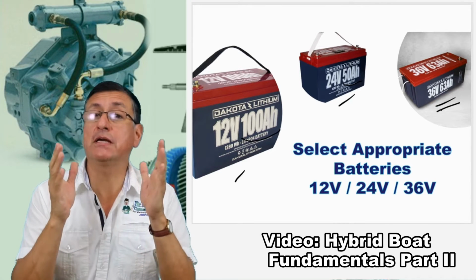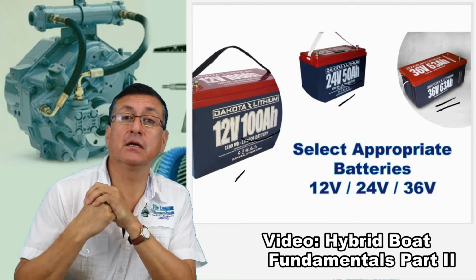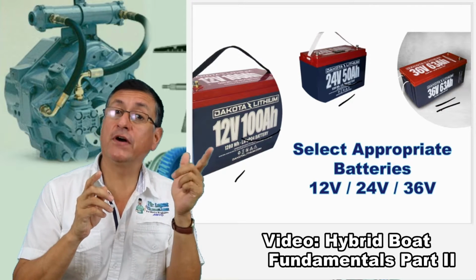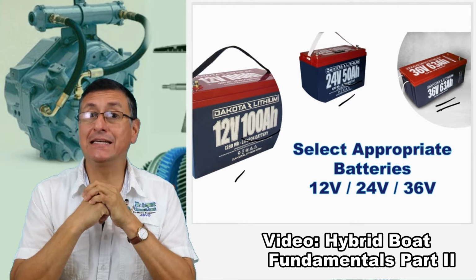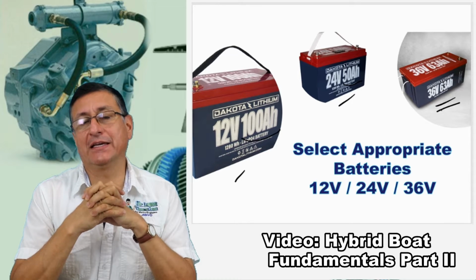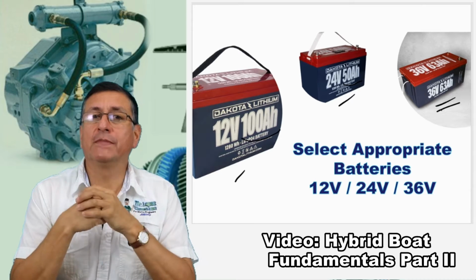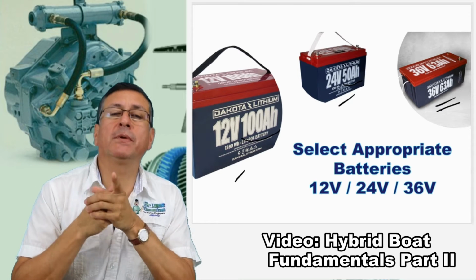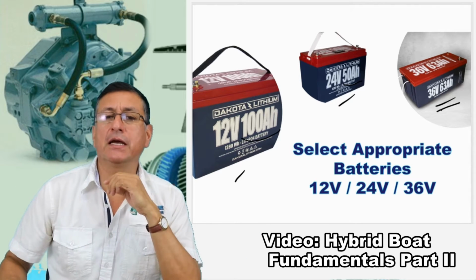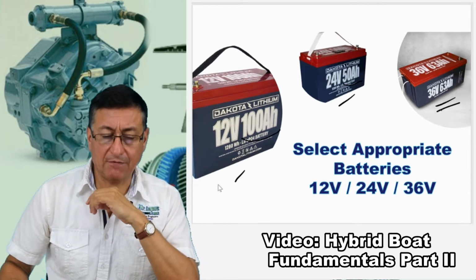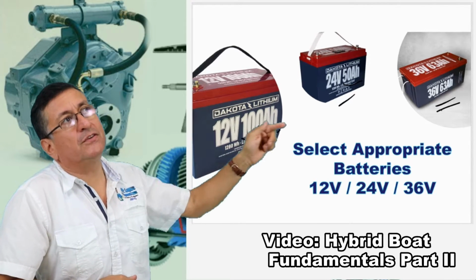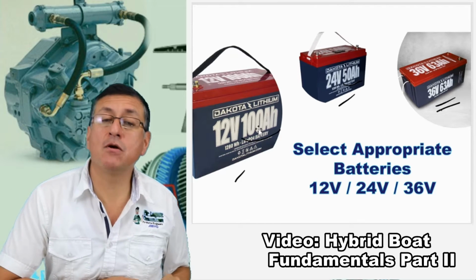If you have 12 volt batteries, you need to connect 1, 2, 3, 4 batteries in series in order to get the appropriate 48 volts. But remember, when you connect in series, what happens with the intensity? The intensity stays constant. In that particular case, I have 100 amps per each battery of 12 volts. If I connect 4 batteries in series, I have 48 volts, but 100 amps.